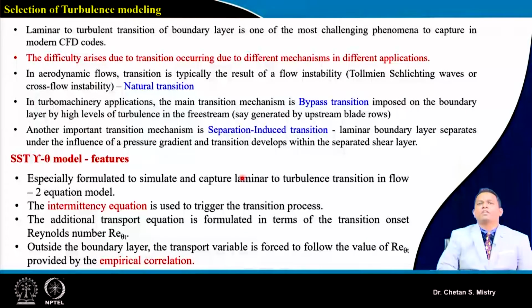Under that configuration, it is very difficult to understand what is happening on a blade suction surface, because how my flow transitions and from where that transition is occurring is of our great interest, because that is what will decide how my flow will behave towards the trailing edge.